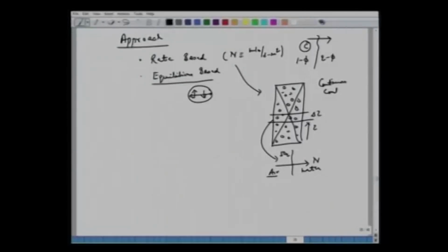So this arrangement is continuous contact, which you can have in absorption, you can have in adsorption, you can have in drying as well. This is just an example. There you apply rate based approach. Equilibrium based approach, what do we do? Now we are talking of cascades. We are talking of stages, trays, certain devices, contactors.